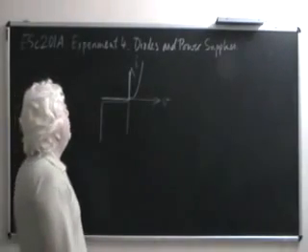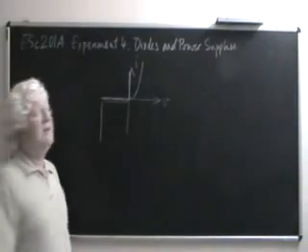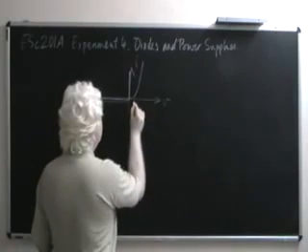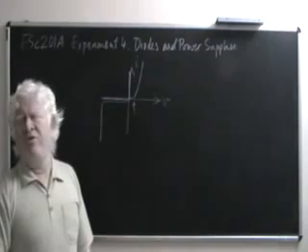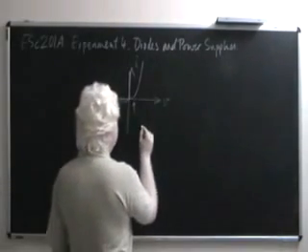Very clearly, you can observe two things about the forward behavior. One, that there is a so-called knee voltage or cut-in voltage of around 0.6 or 0.7 volts. You might even observe 0.8 volts in the laboratory.